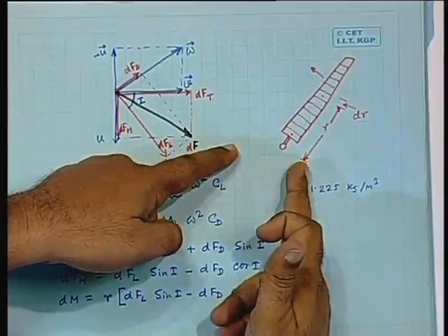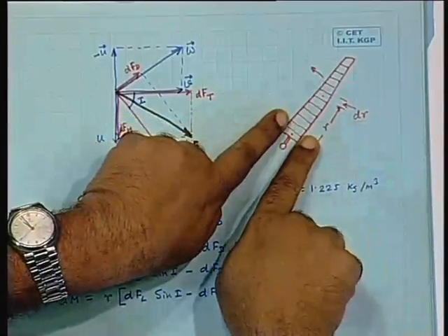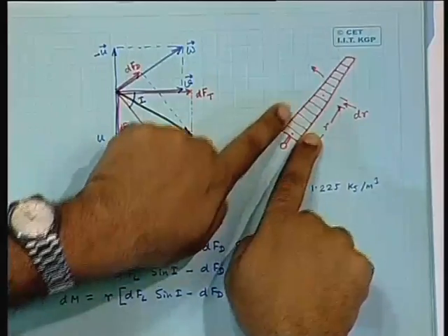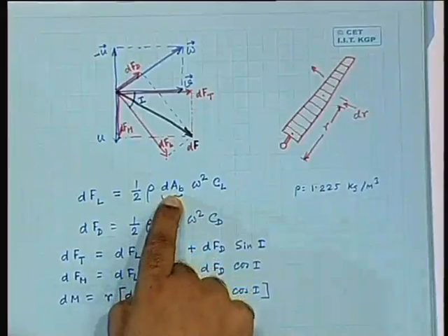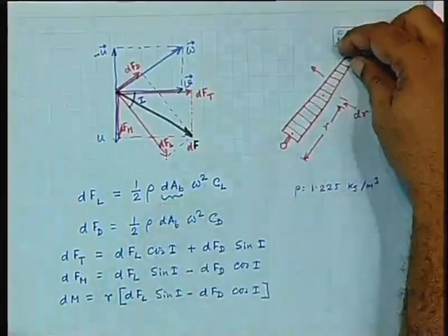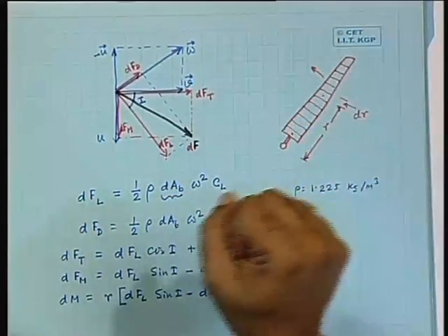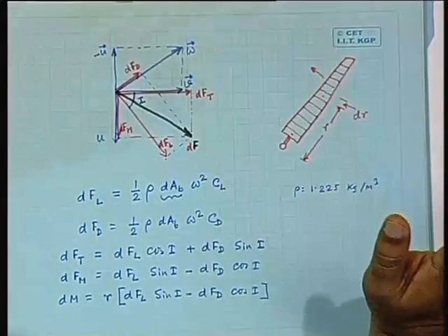Generally, people try to avoid this problem by two means. One, by using a taper, so that the area inside is bigger than the area outside. Toward the tip, it tapers. As a result, this number, this particular dA, becomes smaller at the tip, and so we can keep the shear force and bending force within the limit that can be withstood by the material.